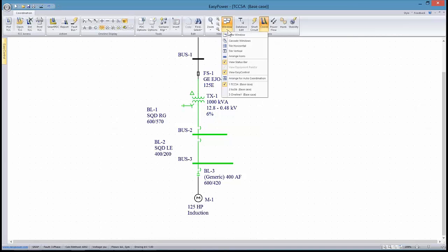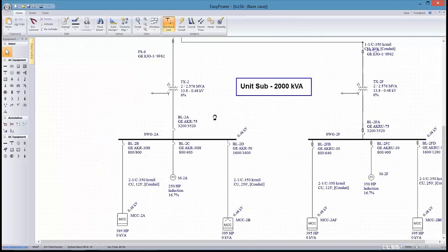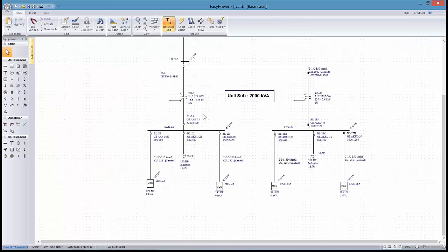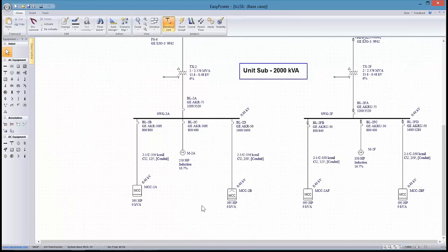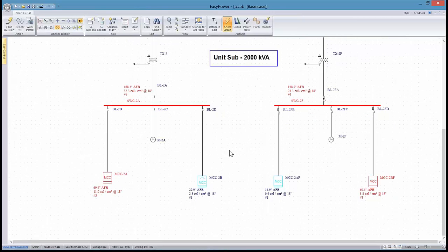Should have an example here. Okay, so here's an example that we use from time to time. We see on this particular bus that though we have a large motor, we may potentially even have larger loads inside the MCC. So let's go ahead and make sure we can change focus to arc flash. We calculate bolted fault currents, and apparently there's some reason to believe that incident energy may need some optimizing as we look at the different places on the curve.